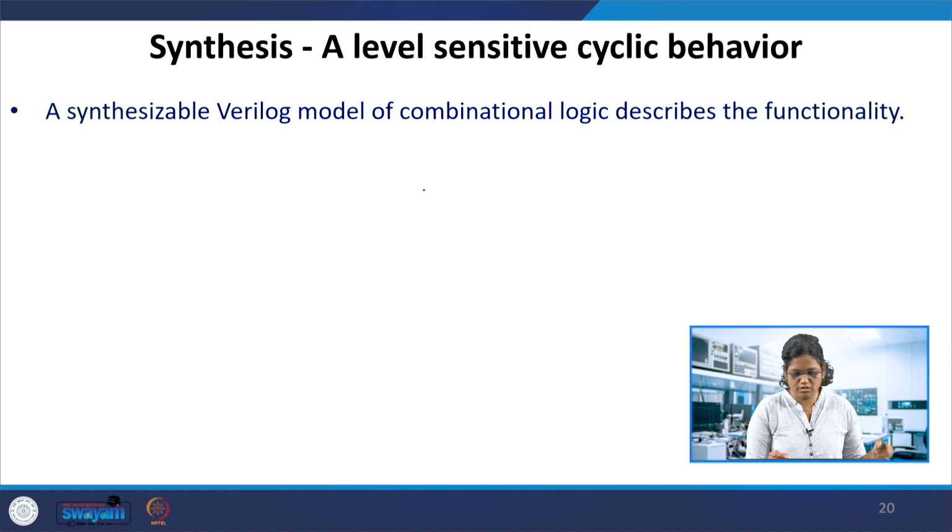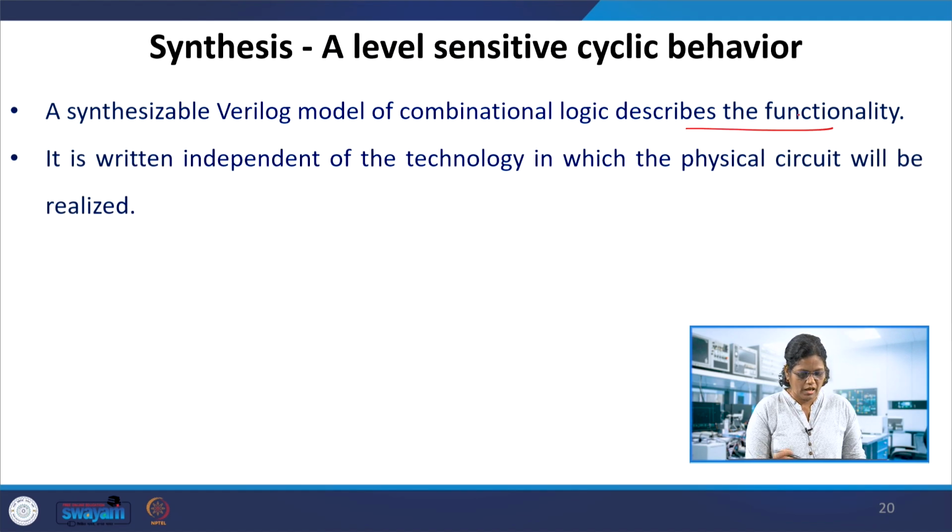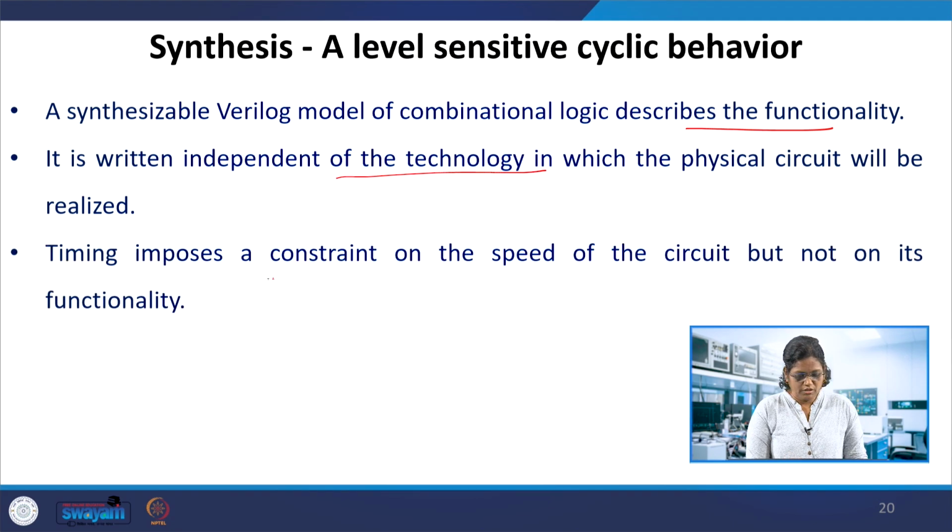A synthesizable Verilog module of combinational logic describes the functionality of the code, and it is written independent of the technology, the code that we are writing. It can be dumped into any of the FPGAs, so the circuit which is to be realized is common, whereas the technology is not common here. And when we give the timing constraints, that is the only time when you do the timing analysis, that the speed of the circuit is tested.